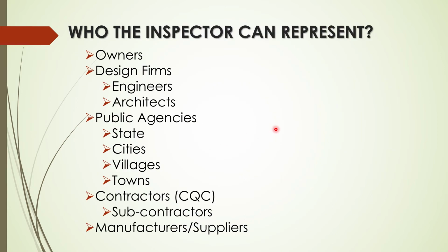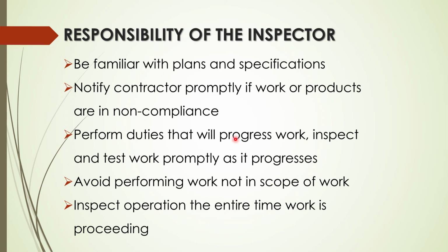So who can you represent? Owners, design firms, engineers, architects, public agencies, states, cities, villages, towns, contractors, because they have to do construction quality control, subcontractors, manufacturers, or suppliers. What is the responsibility of the inspector? Be familiar with plans and specifications. Notify the contractor promptly if work or products are non-compliant. Perform duties that will progress the work, and inspect and test work properly as it progresses.